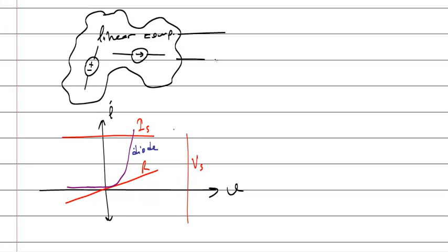From that circuit you look at two cables and you calculate the open circuit voltage. You take two points, you measure the voltage. That voltage is the Thevenin voltage. That's it.